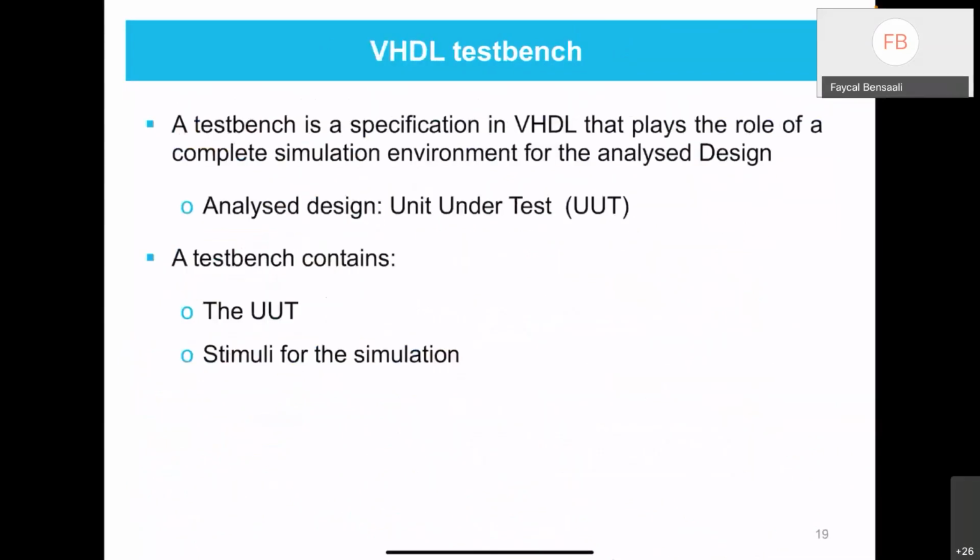So, as I told you, we need to write a test bench, a VHDL code, another code, which has a special format. And I'm going to show you the format later on. So the test bench, as you know, we need to include the stimuli, or the stimuli are the test cases, using the wait statement and process and so on.